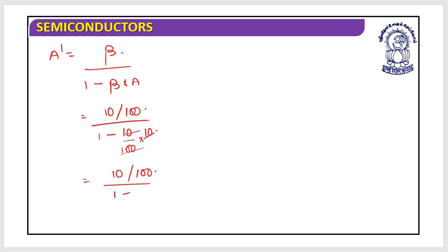So this equals 1 minus 1, and this has reached the Barkhausen criteria. So if they have reached the Barkhausen criteria, this would be infinite. So now it has entered the oscillatory region. Yes, you do not need to provide any input, but it will work for you and provide you the output. I hope this is clear.